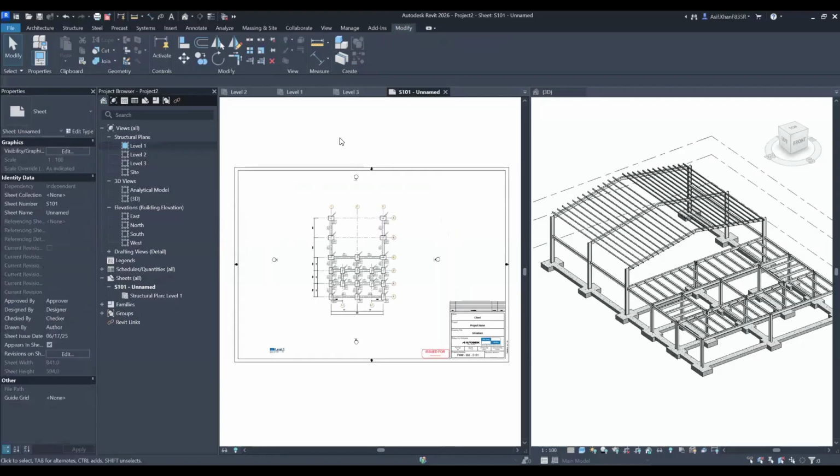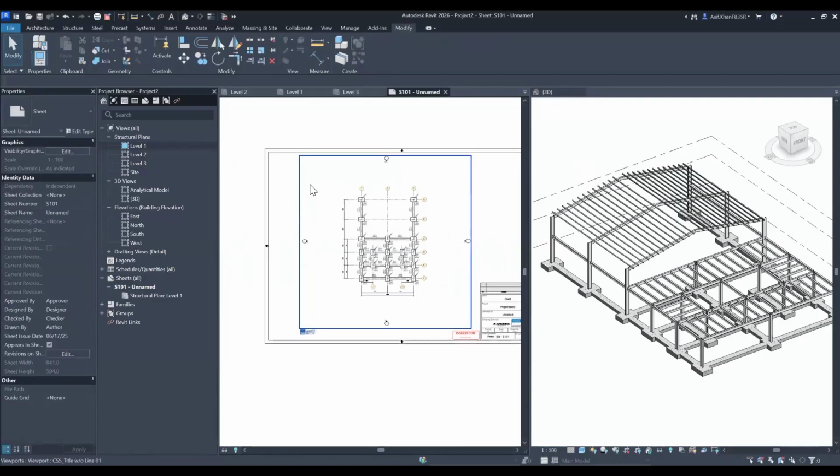Imagine when we have been doing this in AutoCAD, we have been taking a view, putting a layout from template, then creating the view window, then placing them, setting annotation scale. I mean, that's a lot of jobs, I think, for me. That's why I want to make it easy. Just create sheet view, just place the views, job done.